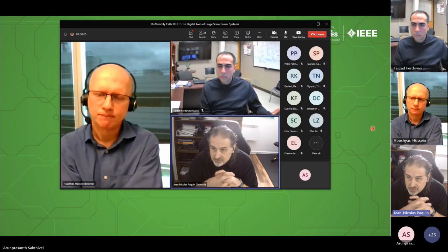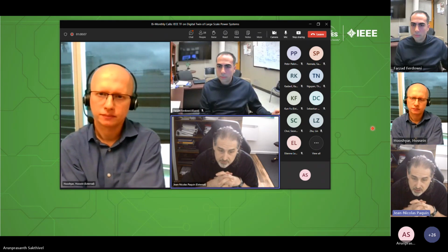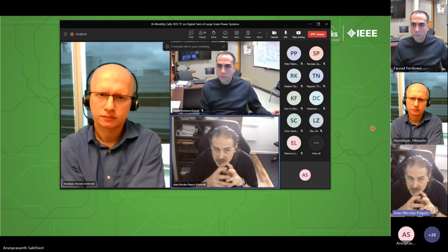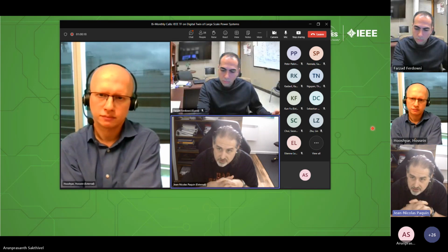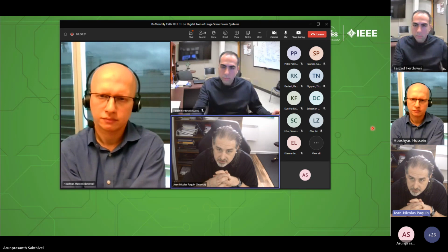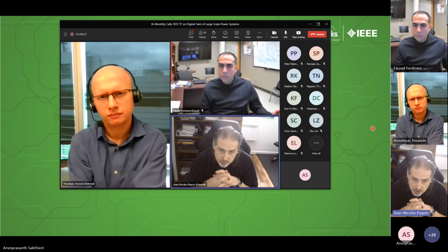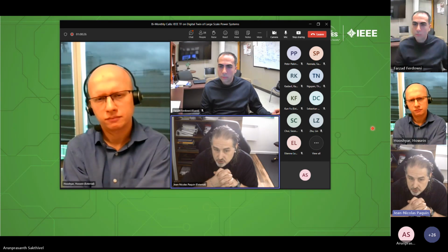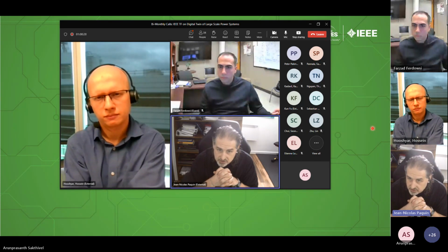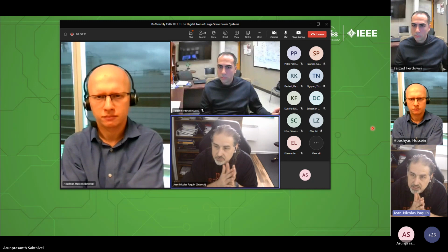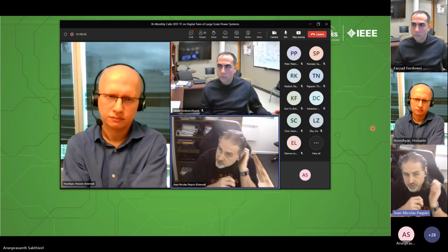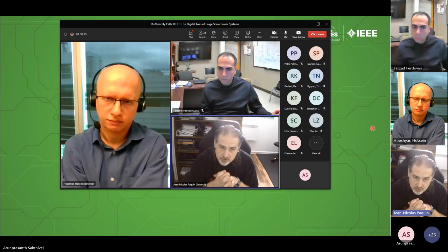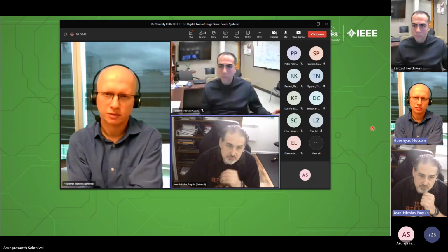And it seems like in cases where you have large penetration of IBRs, you will need to go to EMT simulation at some point. So maybe if you start with the cost of not having the right dynamics represented in your model, and then you go into what is the cost of such a system or such a digital twin, it may give you a good idea. I don't have a clear answer. It's very general what I'm saying, but I think it's part of the equation as well. Good point.